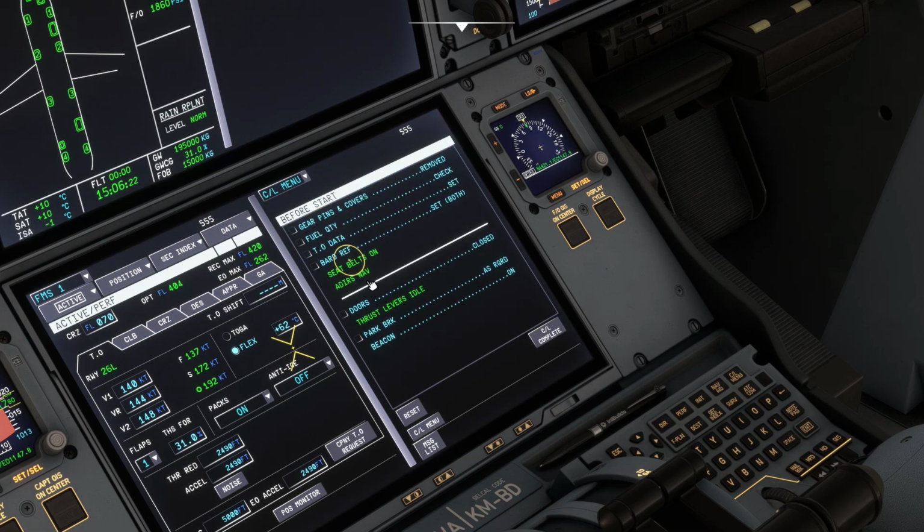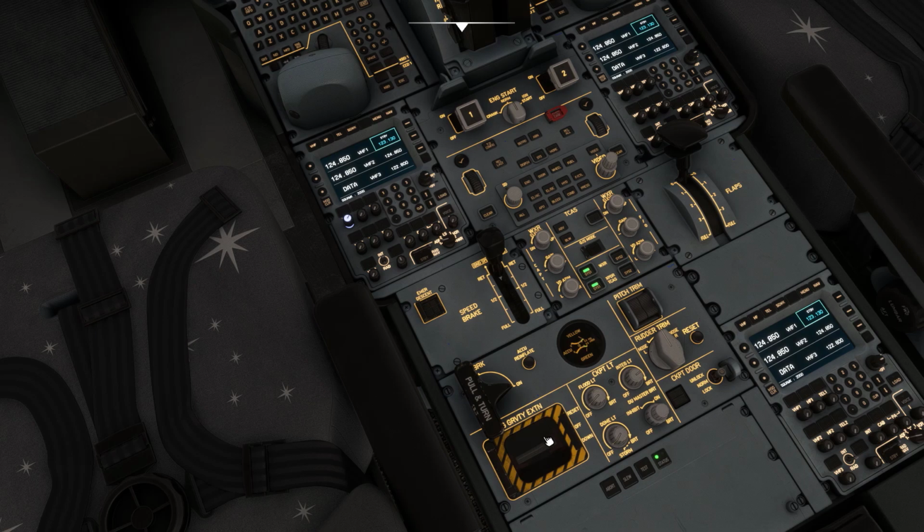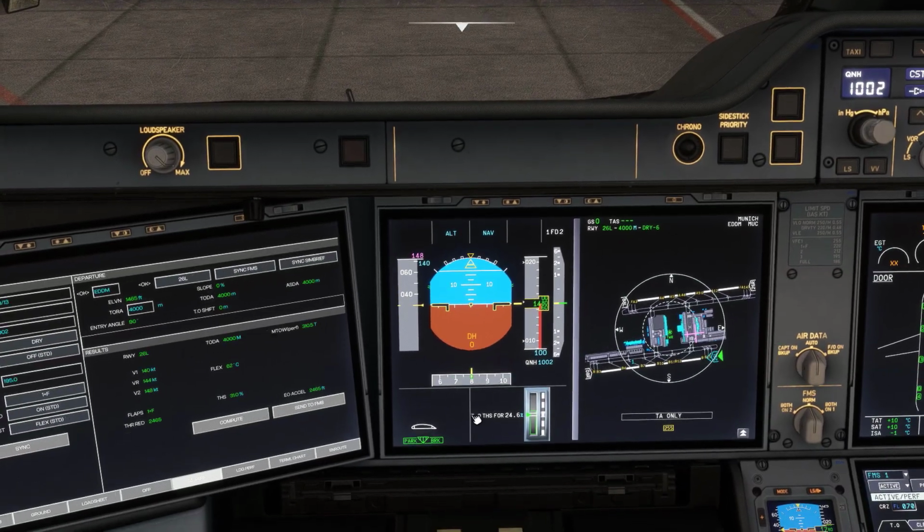Checklist, before start checklist. So gear pins covered, so move, fuel quantity 15 tons, takeoff data, we have 148 V2, barrel ref we have set on both sides, the doors are closed as you see. Oops. The parking brake is set. I'll check that. Check the accu pressure and the parking brake, and it's also indicated down here.